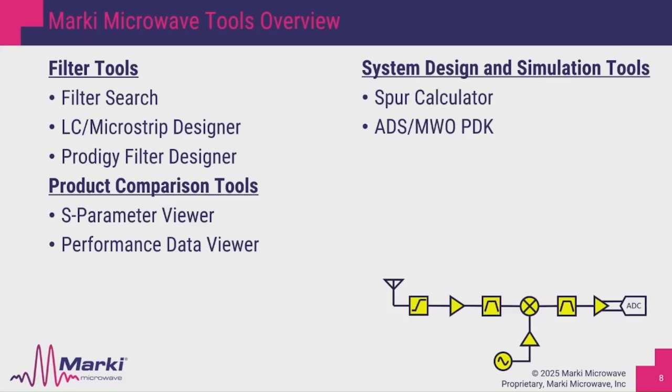And these aren't models that are tuned to fit datasheet data. These are actual design files for a specific device in the catalog. What that means is when you're simulating, for example, the MM10626H, you're not simulating a generic mixer block that we custom fitted to match the measurement. You are actually simulating that device with those specific diodes and those specific Balun architectures. Essentially, these tools here, the PDK, is the next best thing you can get after sitting in front of a VNA and actually testing hardware. They save a ton of time during the system design.